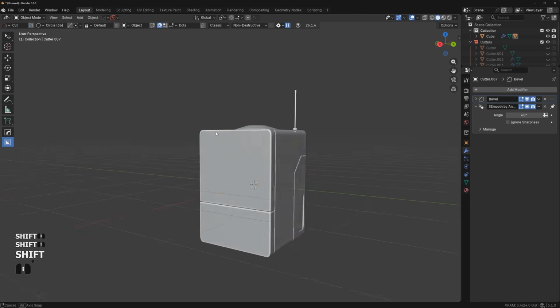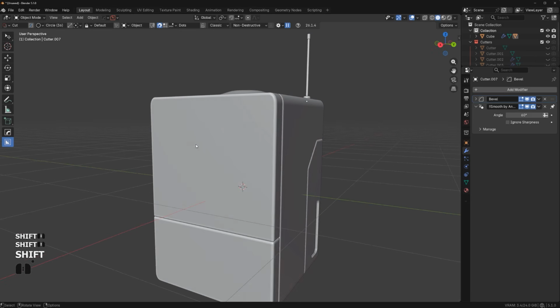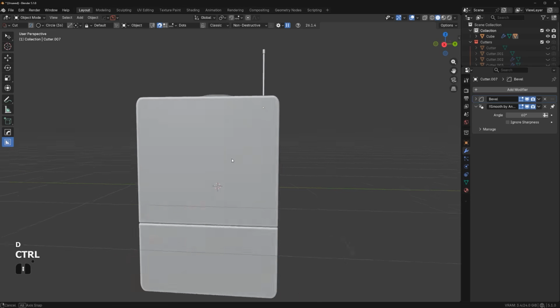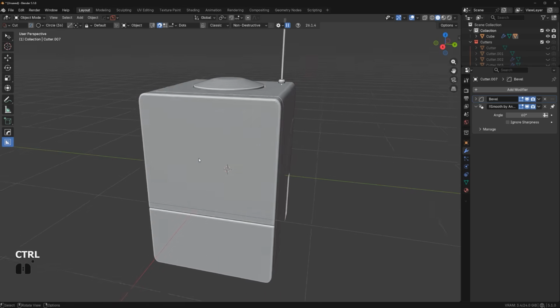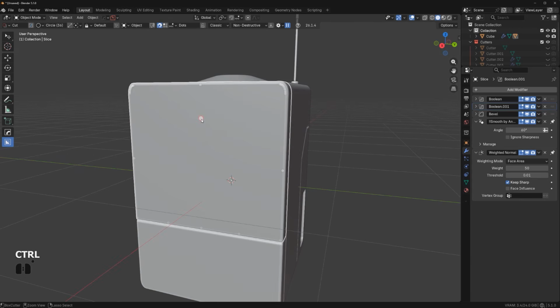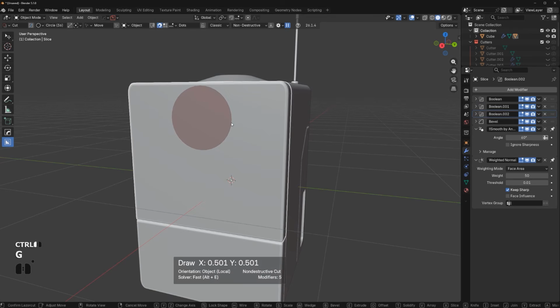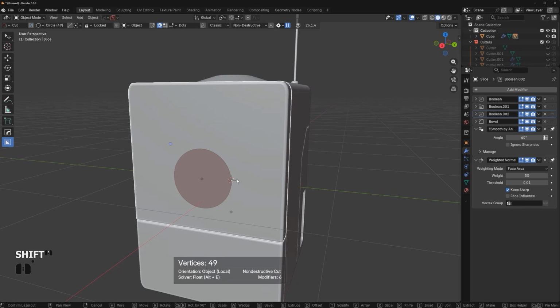Awesome. Now here in the front, we're going to have a lens, or two lenses. So let's just grab a lens here. So hold Control again. Somewhere here in the middle. There we go. And let's grab a larger one. So G, Y, and pop it down. And this could be, so hold Shift and scroll up to 50 maybe, 50 verts. You can see in the top here. And I'm going to cut it in.